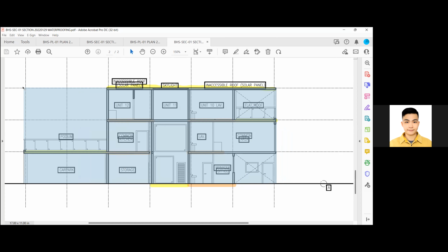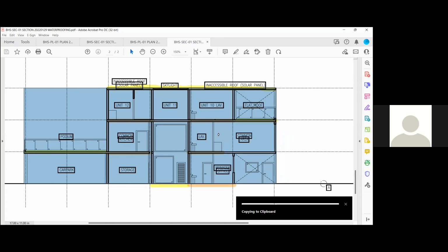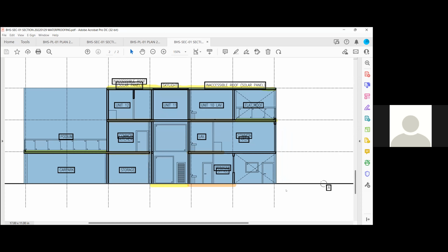And that is just the size of the floor joists, and you have to add in the floor panel, which is typically 3/4 inch thick, and your flooring, and then your chipboard at the bottom, all of those kinds of things. That's going to add to the thickness of the floor.